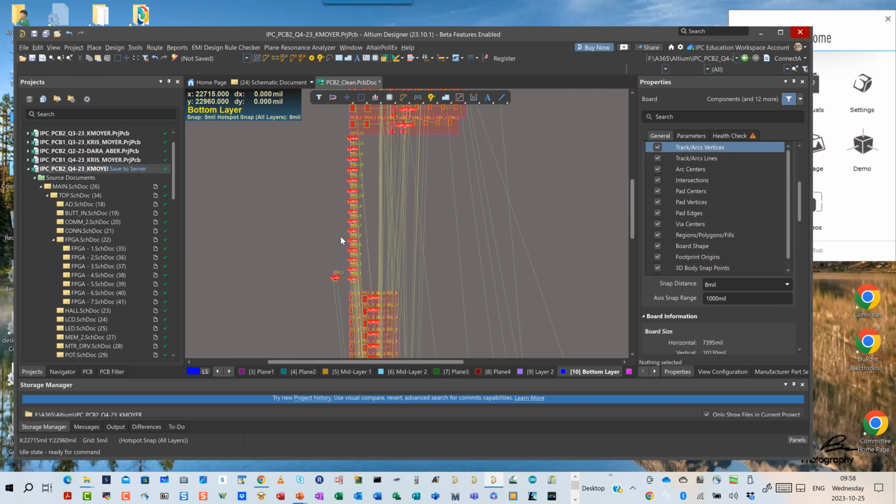I haven't played with it yet, but copy room formats was originally intended for these hierarchy designs because of the way the hierarchy works: every component gets the same base designator, like R1 or DS1 or whatever it is, and then an underscore and an index. So R11, R12, R13, and so on.